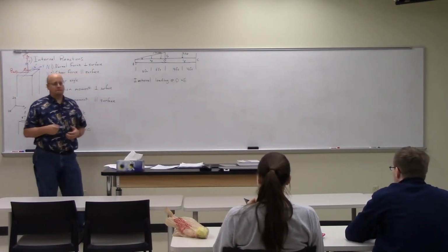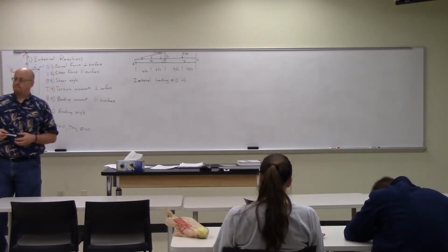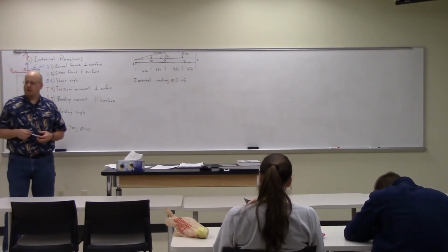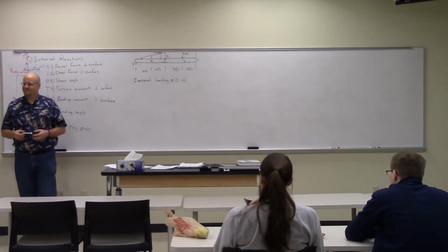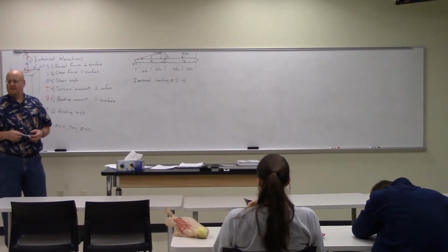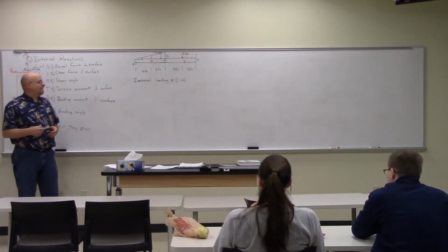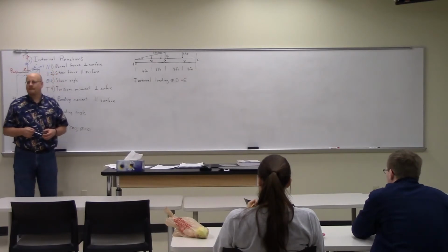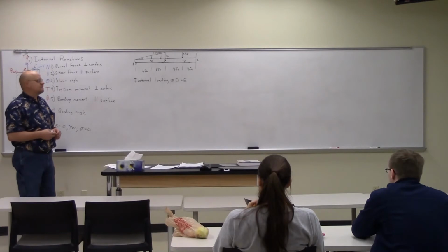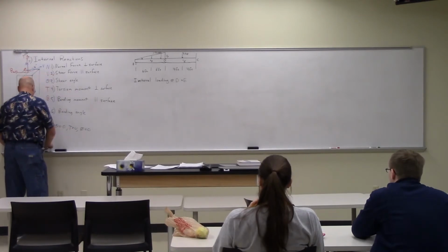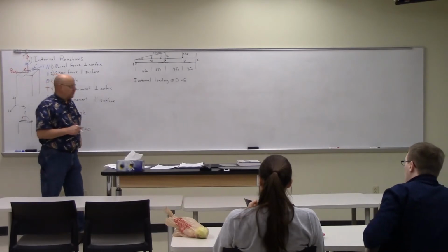Okay, so what do we do? What's the first step? Yawning, apparently, is the first step. I take the, is that a distributed force up there? Yeah. I take the integral of the distributed force and find the centroid of that shape of the distributed force and turn it into a point load. That was my first choice, but that's an allowable first choice.